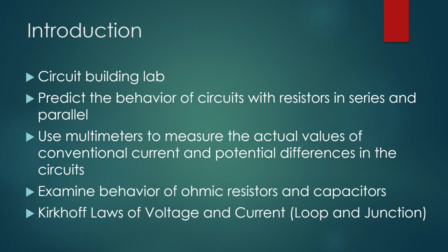And of course, there's always going to be error in the electrical components, because as batteries are used, their voltage drops over time, wires can be faulty, resistors can be a little faulty, and ammeters can be not calibrated. So there are a bunch of different pieces of error associated with this lab.